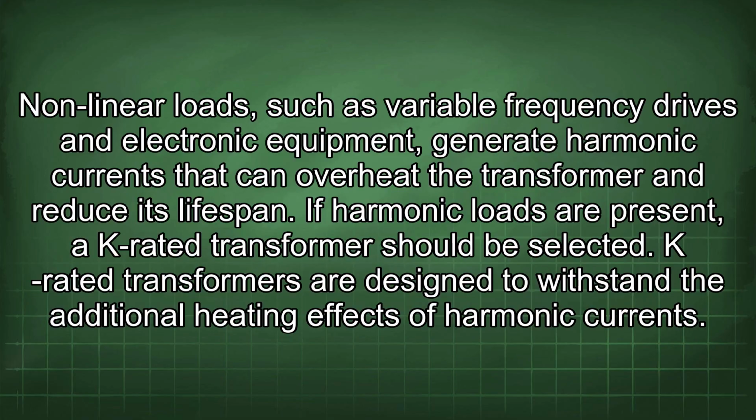Nonlinear loads such as variable frequency drives and electronic equipment generate harmonic currents that can overheat the transformer and reduce its lifespan. If harmonic loads are present, a K-rated transformer should be selected. K-rated transformers are designed to withstand the additional heating effects of harmonic currents.